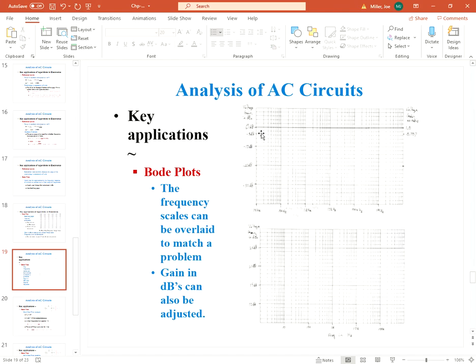Interesting thing to note, this minus 3 dB point corresponds over here to a voltage gain of 0.707. Now, an example of what I'm saying is the frequency stayed the same down here, but let's take a look at the gains. This is a gain of 10. At this, you go up 5 from the bottom, you're at 10, then you go up 5 more, you're at 15. So this must have been 5 dB. You can start it wherever it makes sense for what you're plotting. This is 10, you go up 5, you're at 15, 5 more, 20, 25, 30.